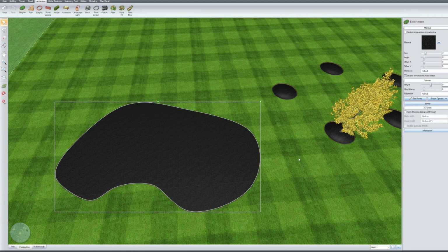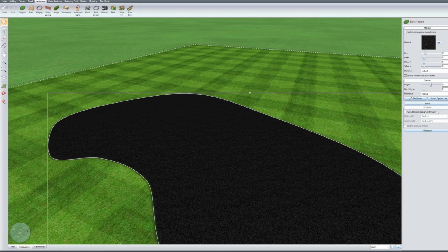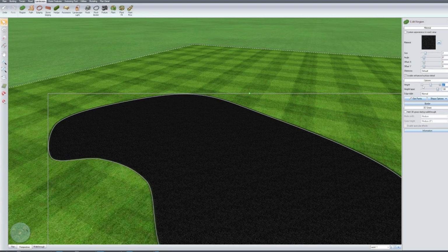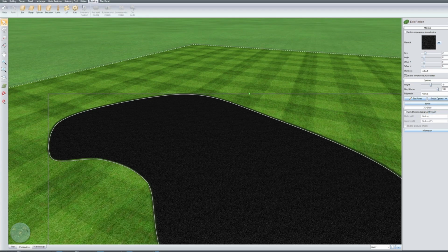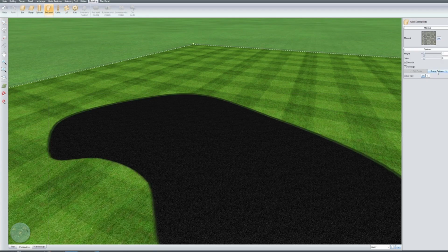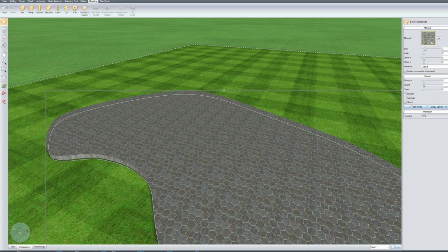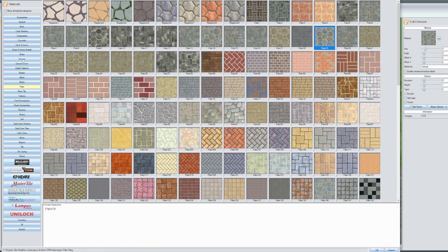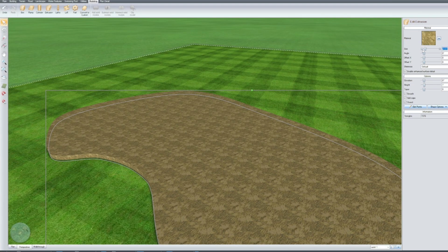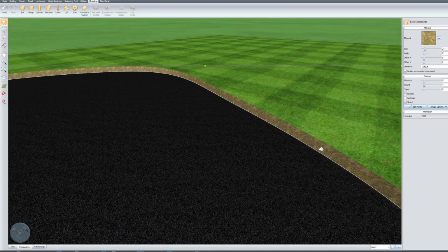It's really bad drawing there, but something like this. Again, you do it really quick here. We're going to go to 100. We're going to drop this down 1, 2, maybe 3. We're going to copy it. We're going to go to modeling. We're going to go to extrusion. We're going to paste the shape in there. We're going to change the material to ground, here, maybe turn the size down a little bit. I'm going to turn off the caps and we're going to lower this down.